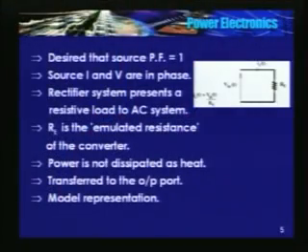How do I achieve this? You can achieve it using a switched mode rectification. In switch mode rectification, the power factor is approximately equal to 1. So the angle between the source voltage and the source current is 0. In other words, for the source, this entire switch mode converter along with the load appears as if it is supplying a resistive load. I will repeat, the angle between source voltage and source current is approximately 0. So for the source, the entire system, the rectifier as well as the load connected to the rectifier, appears as if it is feeding a purely resistive load.